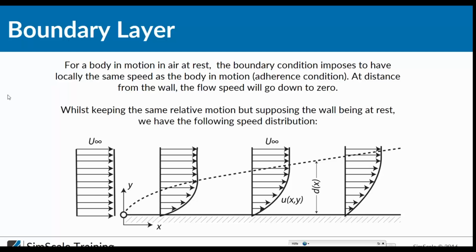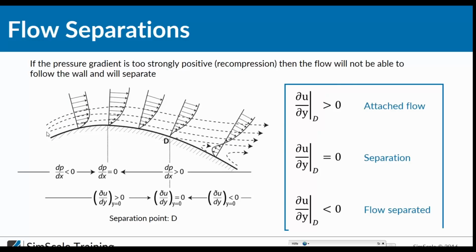Here we have a curved plate. Just imagine we have the flow coming from the left side. And one thing which is very important is to understand the relation between pressure and velocity. So inside the flow field, the pressure, which we can divide into total pressure, dynamic pressure, and static pressure, is in the end the energy in the flow. And if this flow is following a surface, it's running against a pressure gradient. It means the pressure is changing in this direction.